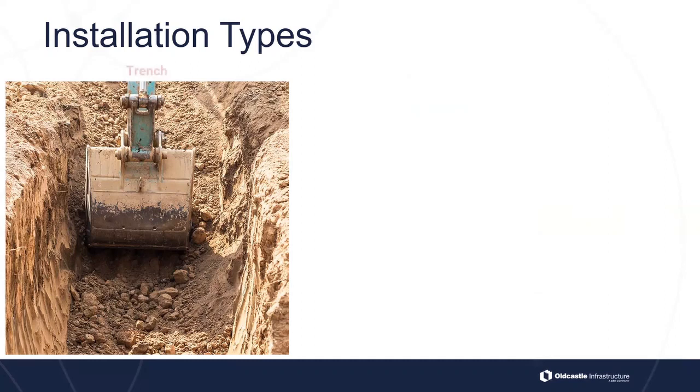Now, the benefit of a trench installation is that because you've got the in-situ soils around the pipe, they're already in place, they're already compacted, they're already stable. Should be, hopefully they're stable there. But what it's going to do is, as we backfill, that trench wall is going to absorb and use some of that friction forces of the interaction between the new backfill and the existing trench. It's going to absorb some of that load, and that coefficient of friction is going to mean that we don't have as much of a load directly on top of the pipe as we would with an embankment installation.